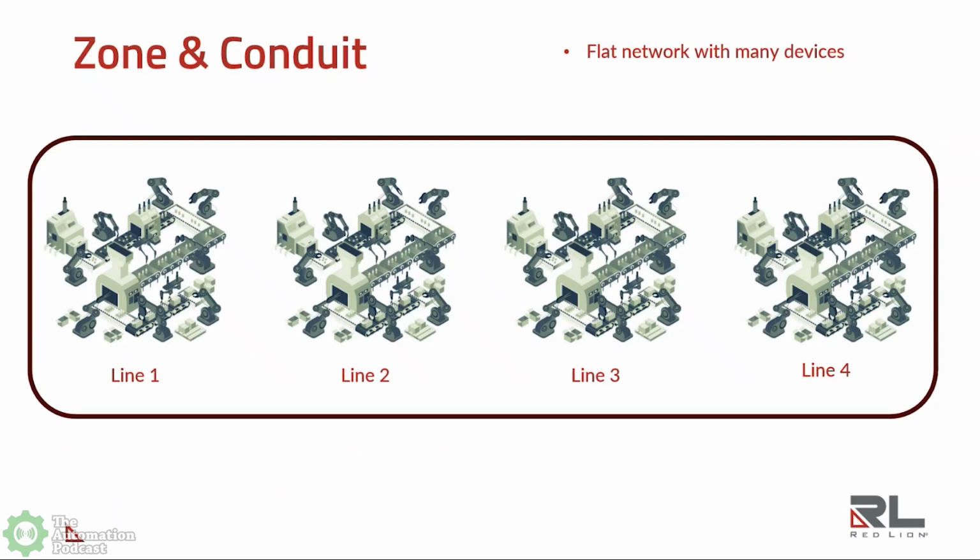But the problem was the laptop that this third-party contractor had was compromised. And the site had not had full patch management implemented throughout their organization, so they had a lot of HMIs that were Windows-based. And so this Windows-based laptop that was plugged into this OT network was able to infect all of the other HMIs on the plant floor that were also Windows-based that were not patched.